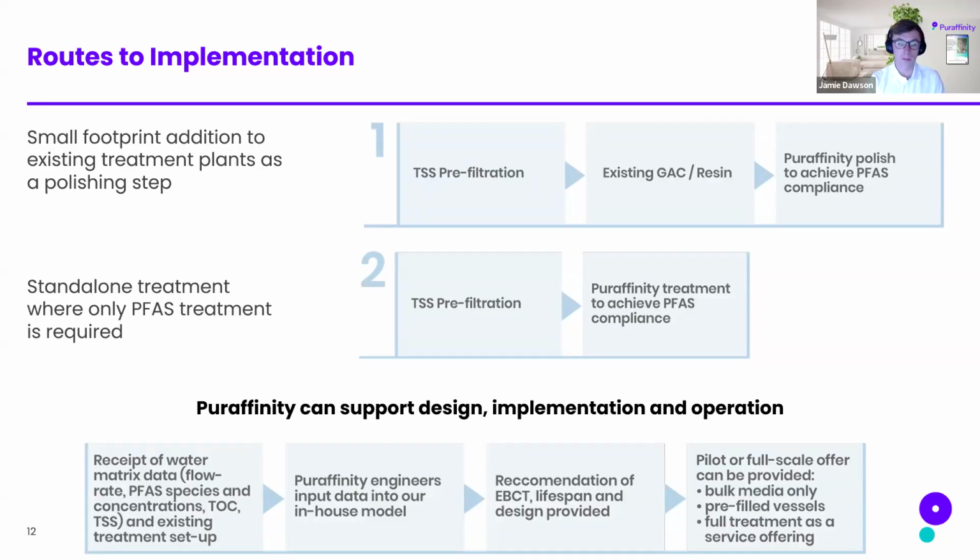So here we might just be placed behind a solids filter, like a glass or sand filter, for example. Then we also have that novel case that I mentioned where clients are now also looking at treating the effluent from RO reject as well, which typically is just discharged into surface water or waste. So also looking to treat that as well because our product deals well with high salinity. So we can support across design, implementation, and operation from anywhere from lab trials to full-scale installations.